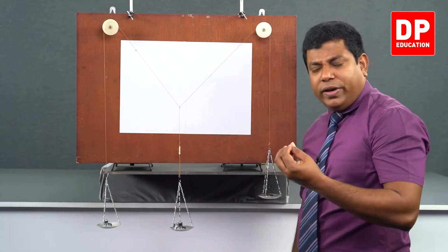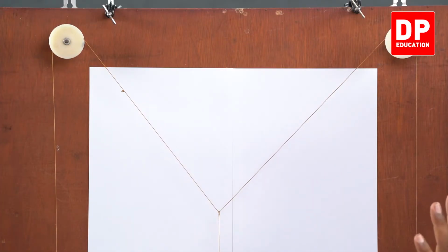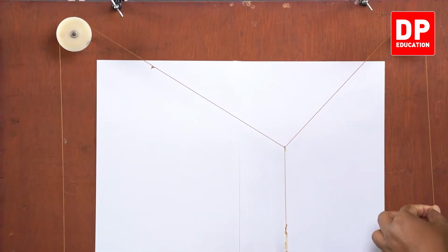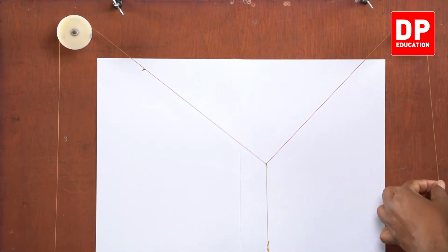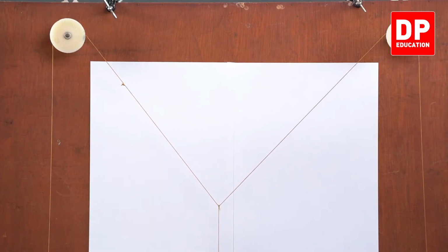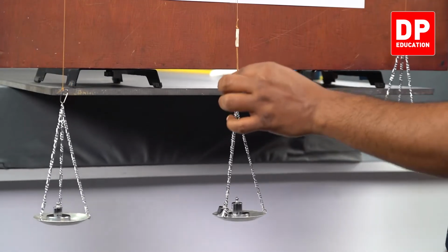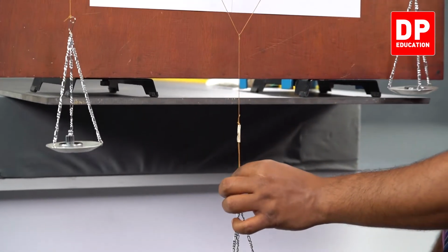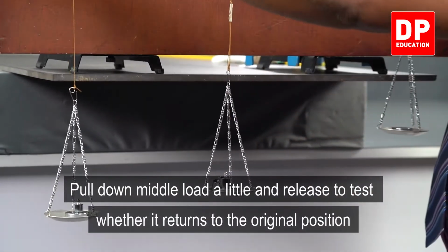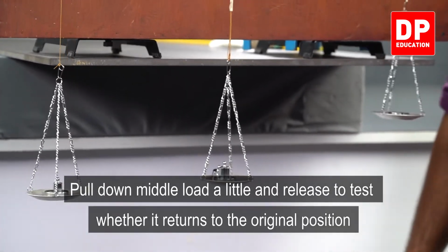So how do we ensure that there is no friction? See, after this system comes to an equilibrium, if you pull one of the weights and release it, the system should go back to its original position. If it goes back to its original position, that means pulleys are smooth. See, let me pull this down, and if I leave it, the system should go to its original position. Let me pull this and see. After pulling it, if I leave it, see, the system comes back to its original position.